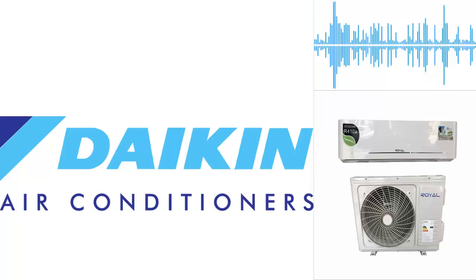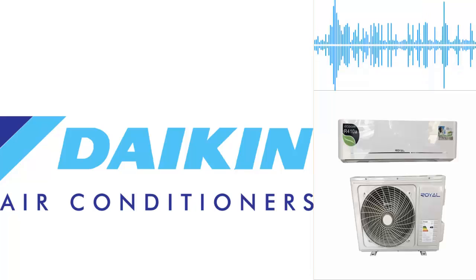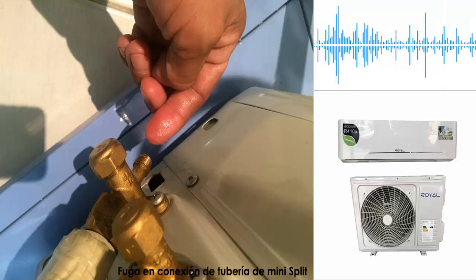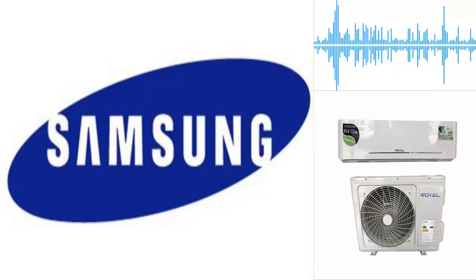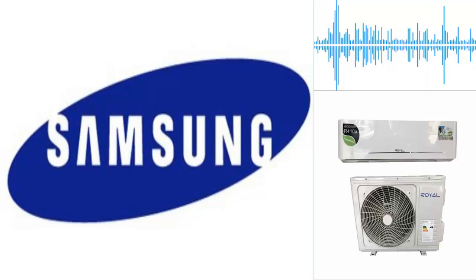In the case of Daikin, error E4 is due to the activation of the low pressure switch, LPS. This indicates that the system detects a lack of gas in the air conditioning. For Samsung, error E4 can be related to forced defrosting, low refrigerant gas levels, a faulty pump, or a damaged temperature sensor, or fluctuations in system pressure.